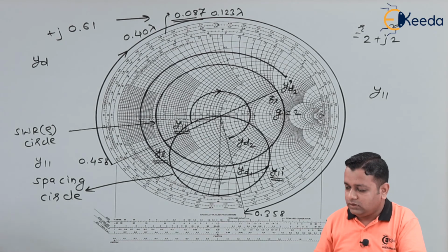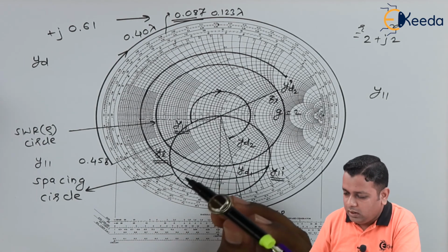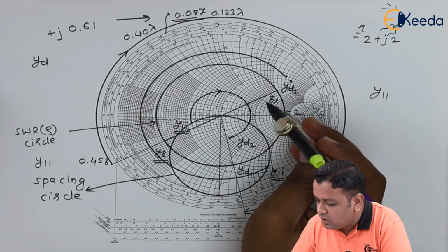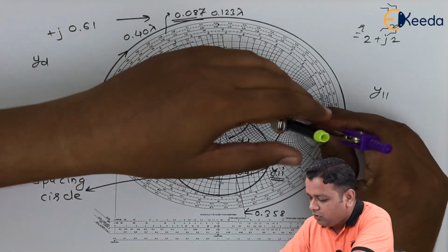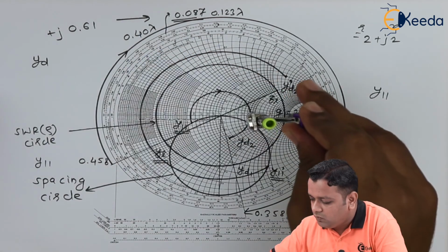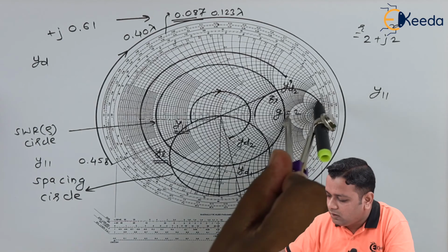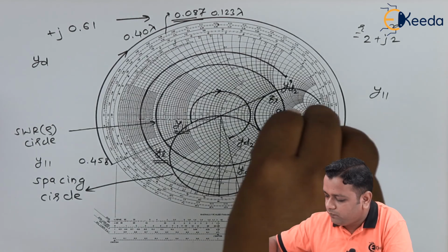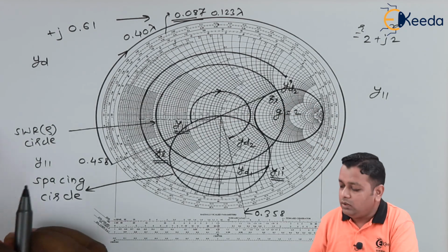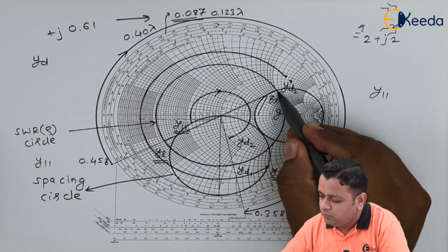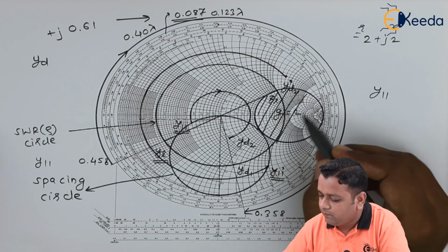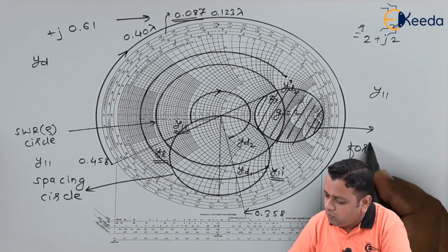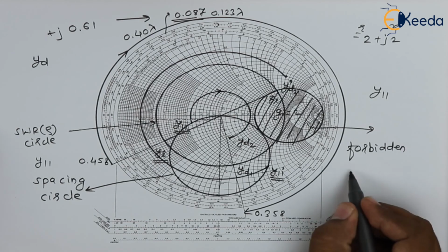So inside this Smith chart, we shall be showing you the area of the g equal to 2 circle here. Inside the Smith chart, this will be the center for g equal to 2 here, and we draw this particular circle highlighted for the visibility like this, the upper half and the lower half here. So here we can show that the shaded portion, if you have it like this, we can name outside that as the forbidden region.